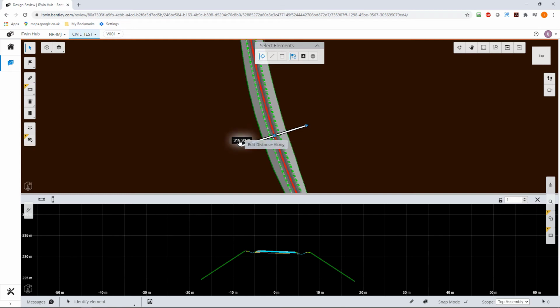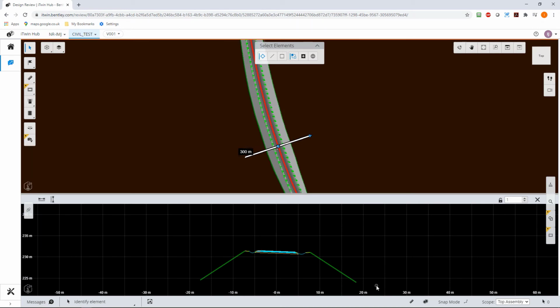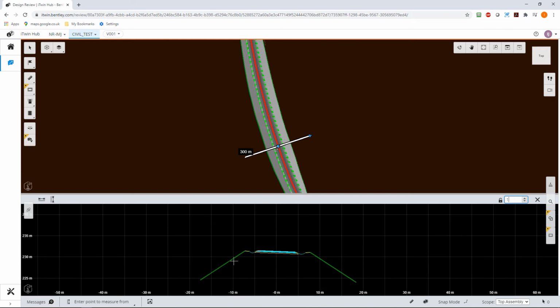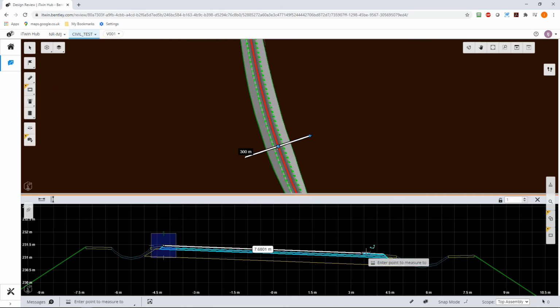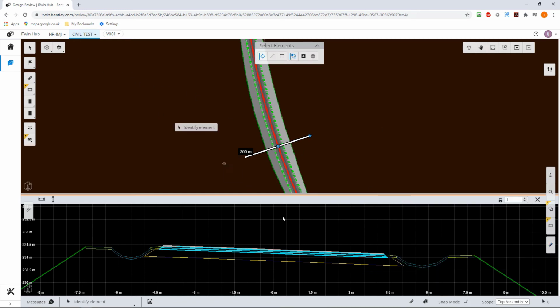So there we go. By the way, you can click on this number here and go to exactly a station that you want to. And this can be stretched vertically if you want to. We can make measurements in here if we want to, or we can change the vertical stretch in here if that's what we want to do. If we do normal measurements in here, of course we're going to get the percentage of our slope in here, and a ratio 1 in 25 and a small amount in here. And if you were to go through the numbers, you'd work those out yourself. So that's quite useful. Let's get rid of that.